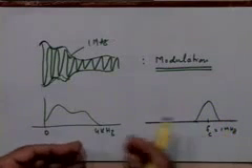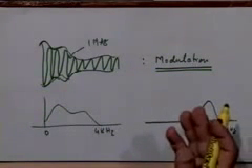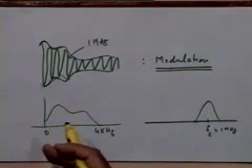And this bandwidth 4 kilohertz is a very small fraction of the center frequency of 1 megahertz. So the lowest frequency components and the highest frequency components are all of the same order, right? 1 megahertz minus 4 kilohertz to 1 megahertz plus 4 kilohertz, they are all of the same order of 1 megahertz. So the antenna size required to radiate this would correspond to 1 megahertz rather than 4 kilohertz.